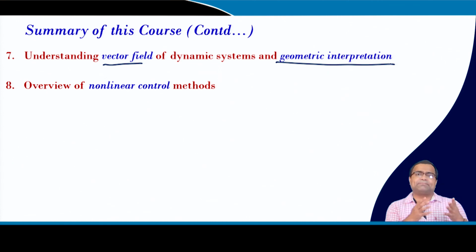That means, if the operating point or the equilibrium point changes or the average quantity changes, then your transfer function parameters also change, and such transfer functions represent a linear parameter varying system, where either the transfer function or state space model, whatever you say, their parameters are operating point dependent.